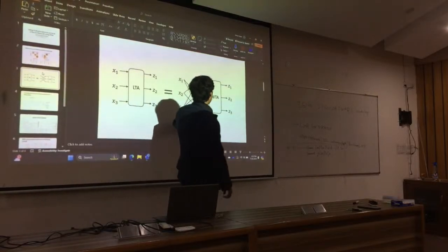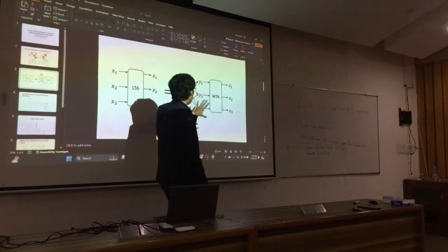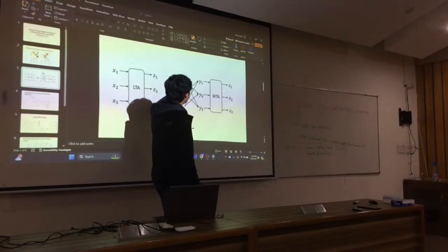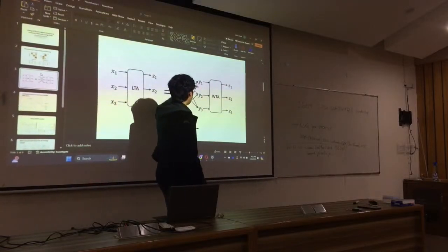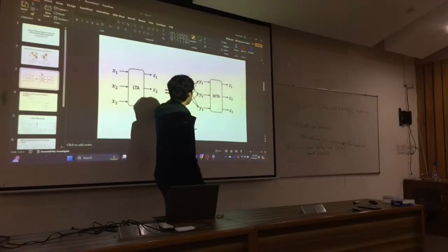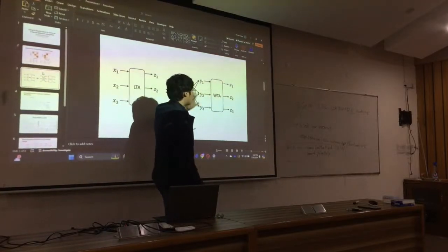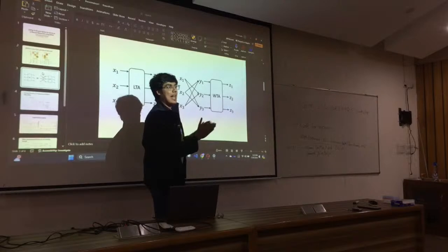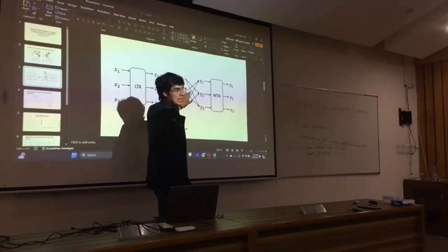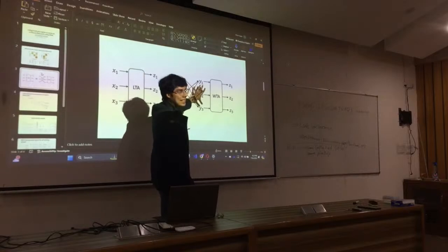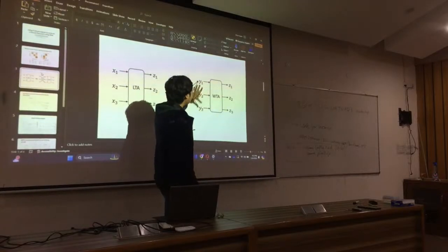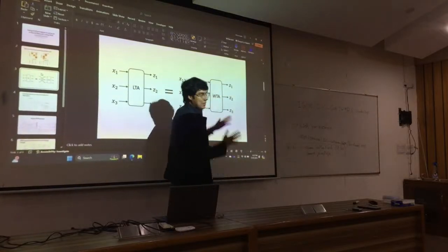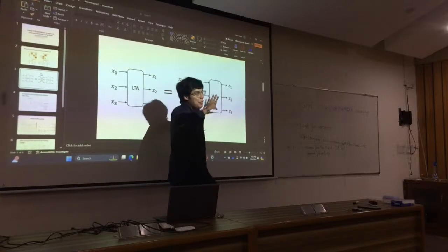In a loser take all circuit, you have the winner takes all circuit in the middle, only that x1 would produce two entities, y2 and y3. x2 would produce y1 and y3. These are placeholders, but they're producing the analogous quantities. So their competing quantities get amplified by the smallest input. Essentially, the smaller the input, the more competing entities would be produced. And hence, if you implement a winner takes all circuit, the smallest input, which produces the most competing entities, would be the output.